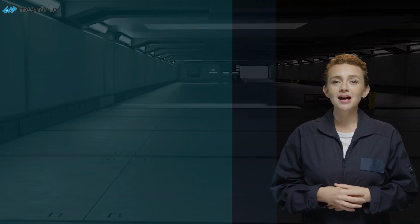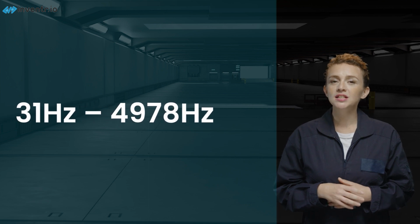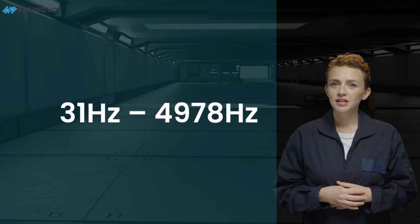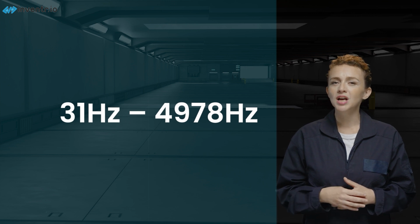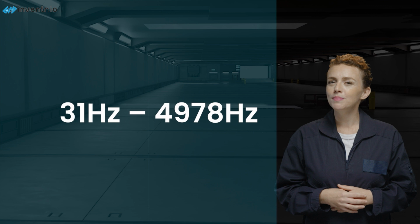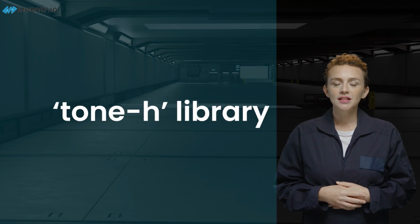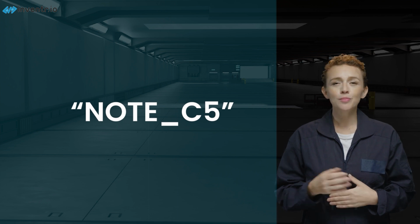Now, in order to make the passive buzzer produce any sound, we need to send it some sort of frequency onto its signal pin. In terms of music, using a different frequency will produce a different sound. It is not possible to generate tones lower than 31 Hz and it struggles to produce higher than 4,978 Hz. If you want an optional additional library, it may be in your best interest to check out the Tone.h library. That way, if you want a specific note, you can say NOTE_C5 instead of some arbitrary number like 523. I've added a copy to your mission resources.